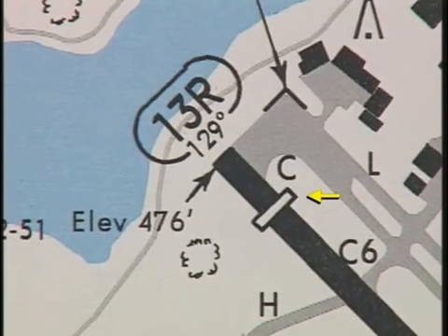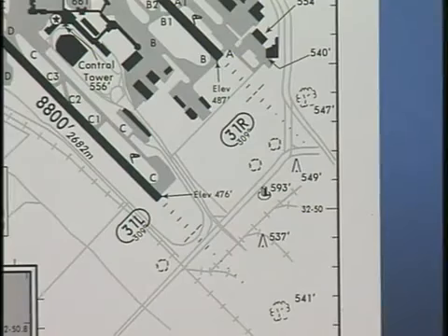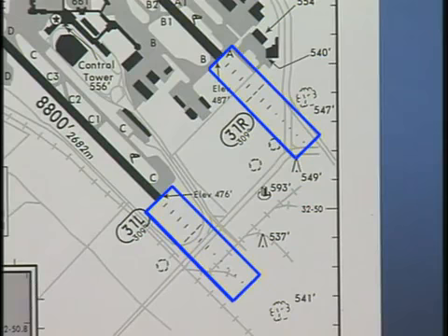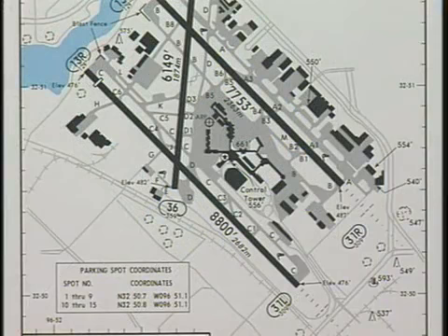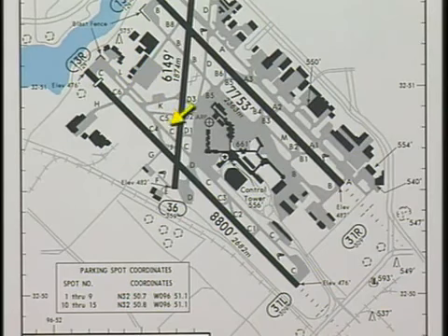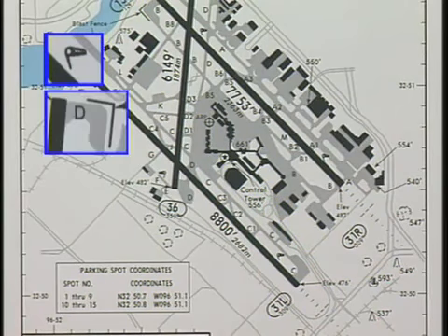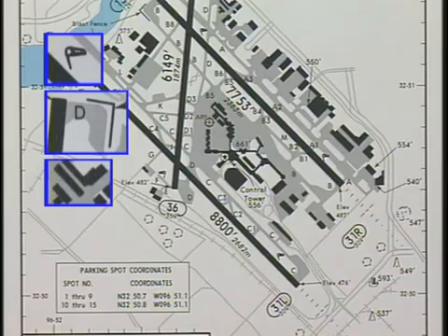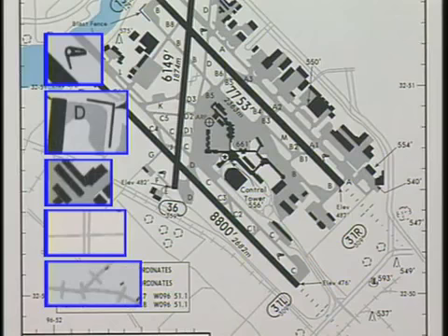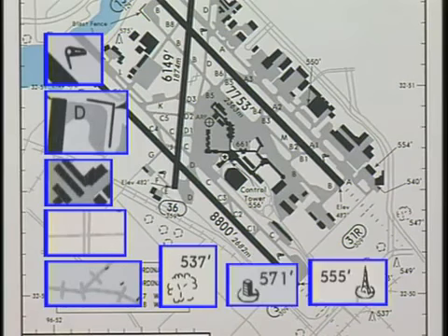These symbols include a bar across the runway, indicating a displaced threshold. If an approach lighting system is installed, a symbol showing the lighting array appears next to the specific runway. When appropriate, taxiways are also labeled with letter designators. Notice that taxiway Charlie parallels runway 13 right and 31 left. Positions of windsocks are marked, as well as blast fences and building locations. Also included on the plan view are roads, railroad tracks, and obstructions such as trees, buildings, and towers.